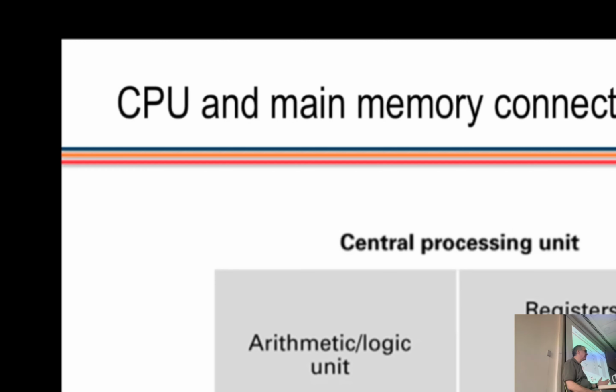So it is very fast, instantaneous, but with some delay. Because in the transistors, you have 5 or 6 transistors here, for example. In the transistors, there is a capacitive effect, and that capacitive effect should be fulfilled for some time in order to stabilize it. So in order to get it stabilized, it takes some time, but it is in nanoseconds range.